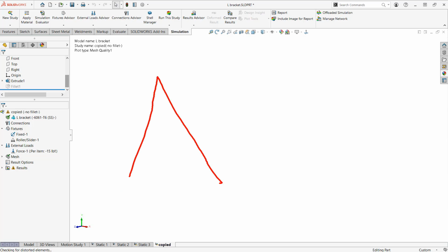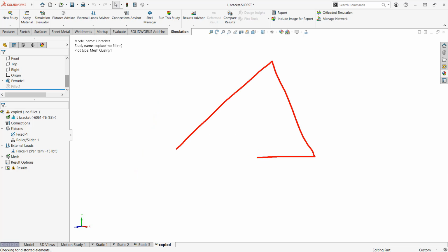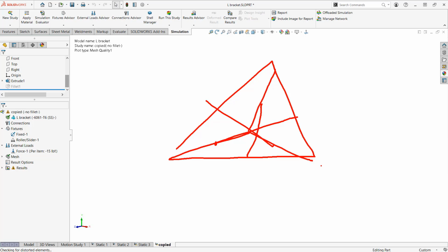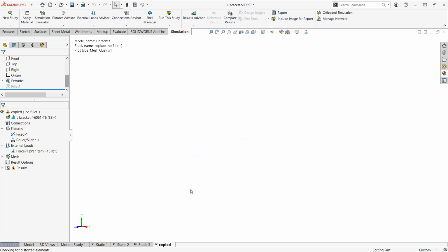Now, I'm going to do this in just 2D because it's much easier to explain. An element's aspect ratio is the ratio of this line height to the base. Okay, I like to think of it that way, but because a tetrahedron is truly in 3D, like this, it actually goes from one side to the opposite side, and it's the ratio of the longest to the shortest one of these. An aspect ratio of 1 is a perfectly shaped triangle or element, tetrahedron.